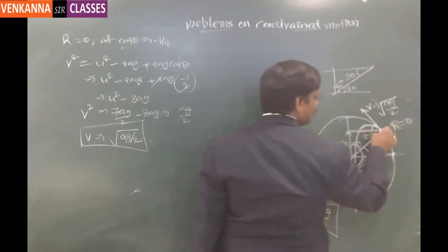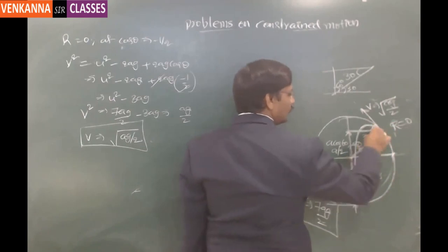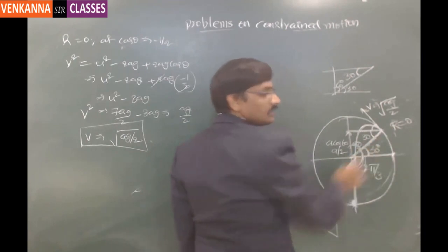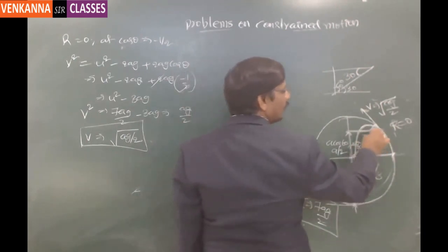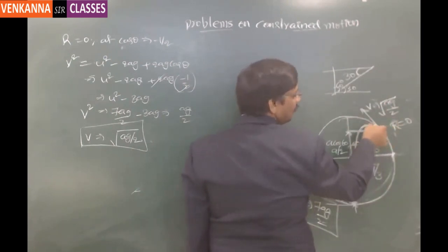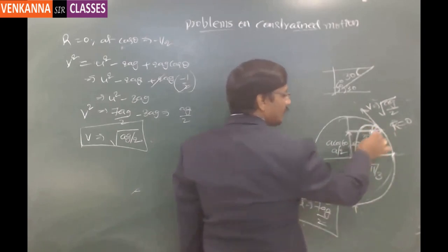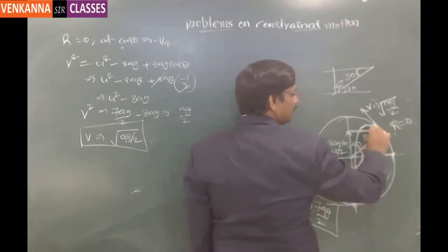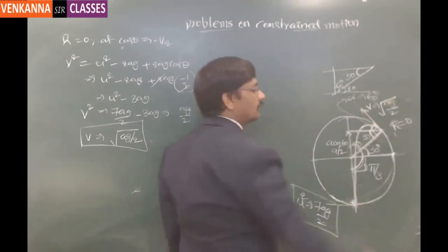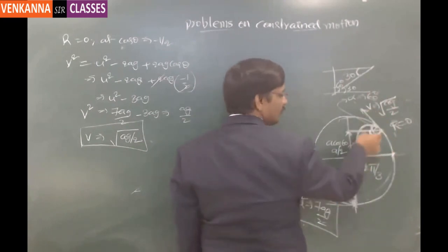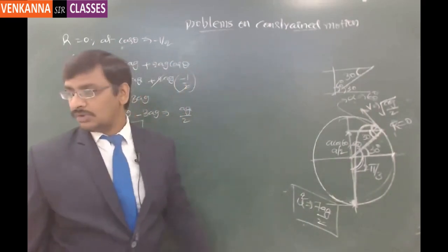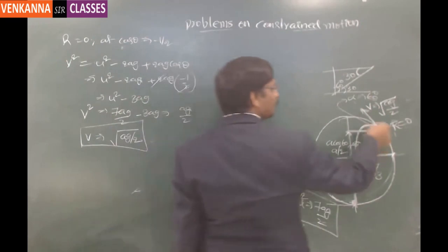See this, this is the horizontal line and this is the radius, and we know that this angle is going to be 30 degrees, because till this point if it is 120, obviously for the horizontal line it is 30 degrees, and the alternate angle is going to be 30 degrees, and we know that this radius and this tangent are at an angle of 90 degrees. So if this is 90 degrees, then this is 30 degrees, hence the only possible value of alpha is going to be 60 degrees. Got it? Because this angle is 90 degrees and this angle is 30 degrees, this is only possible if it is 60 degrees. So that 60 degrees is the projected angle.